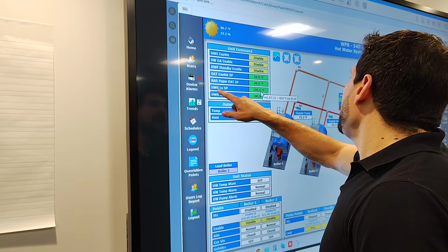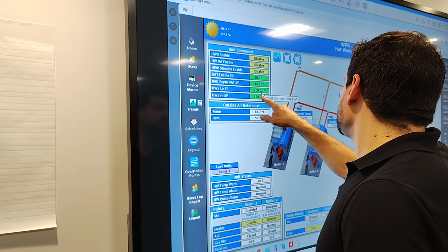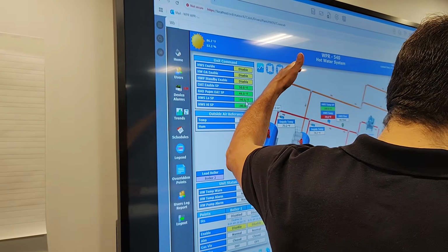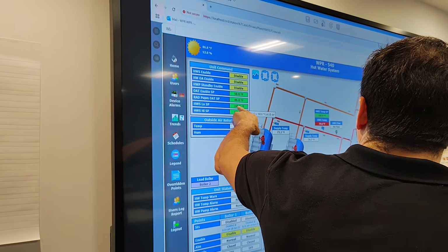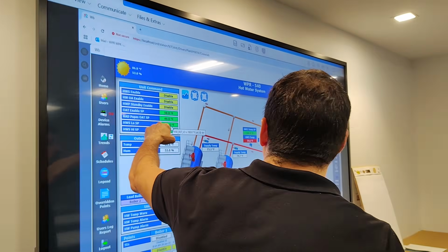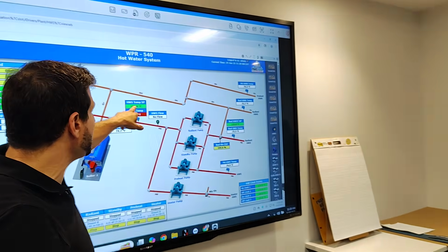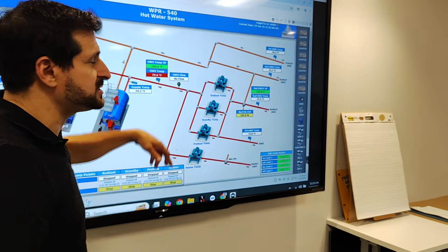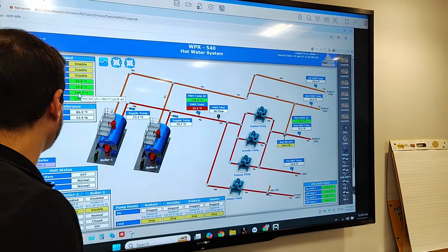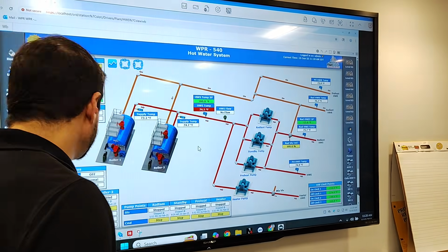Hot water supply low set point and hot water supply high set point are the outer reaches of your reset. So your hot water system will maintain temperatures between 160 and 180 depending on outside air temperature. Since it's hot out right now, you have the coldest set point, which is 160. I don't think you have a problem with those numbers for right now. Leave those, you'll be fine.